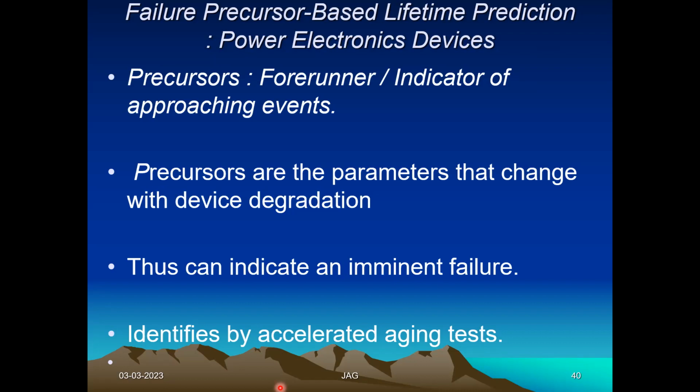So if you were using this MOSFET at 50 degrees centigrade and 10 ampere current, the same degradation could have occurred only after 10 years. That I am achieving by setting the temperature to 150 degrees centigrade and passing 11 ampere current for 1 second or 1 hour. Understand? So instead of waiting for 15 years, I am accelerating the aging process. The same degradation is achieved in 1 hour. Understood? So that is called the accelerated aging method.